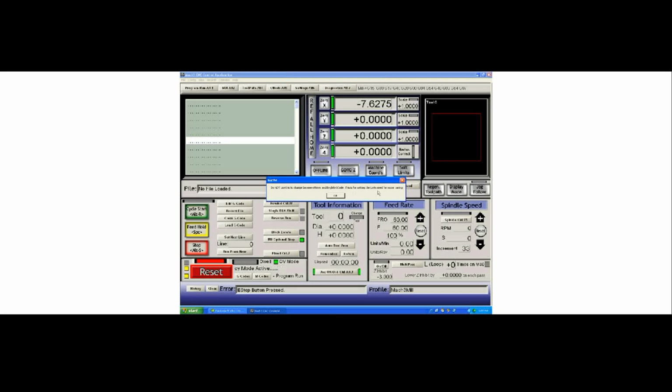There are other ways to switch between English and metric for your G-code programs. If you change this setting, once you've set it, you'll have to retune your entire system. So pick a common use of your system and use that. I'm going to select millimeters because that is my normal use of my system.